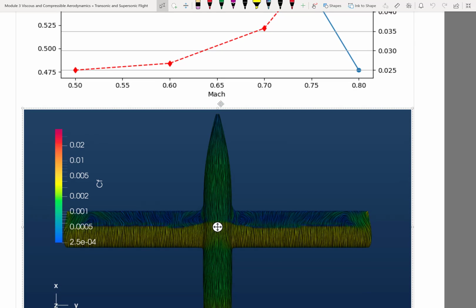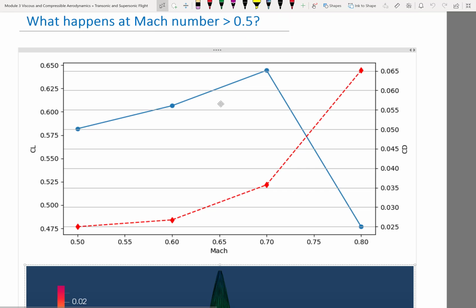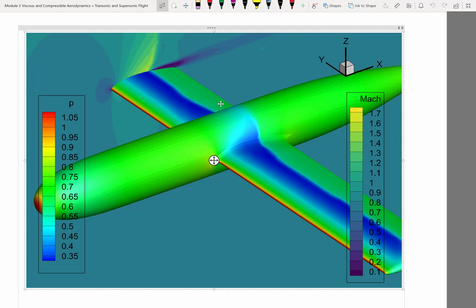you can also spot from the streamlines that the flow basically goes in the opposite direction after it passes the shock. So remember, as the airplane further accelerates, the shock is moving more and more downstream, so the flow separation region actually decreases. And at Mach 1, the whole flow separation region disappears. You no longer have much separation drag, but the wave drag gets more and more because the flow reaches even more supersonic speed before it transitions back into subsonic speed, and the shock gets stronger.